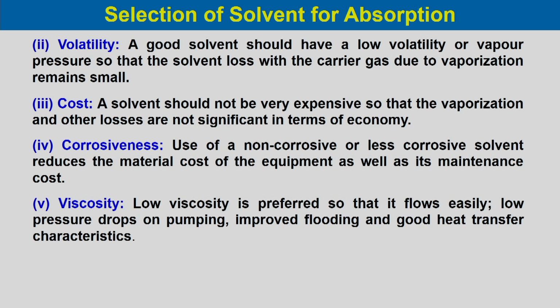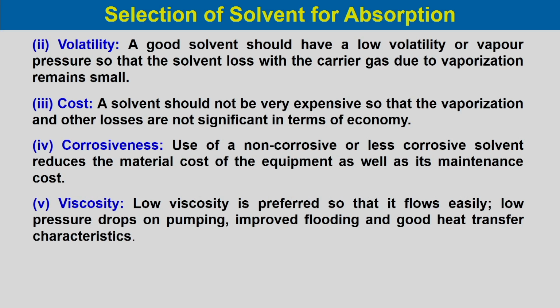So, basically if the viscosity of the solvent is very high, it will increase the pumping cost, and it will increase the pressure drop as well in the column, and the heat transfer of the viscous fluid will not be good. So, the viscosity of the solvent should be as low as possible, so that all these important factors like pressure drop, pumping energy cost, flooding and heat transfer parameters improve. So, solvent viscosity should be less.